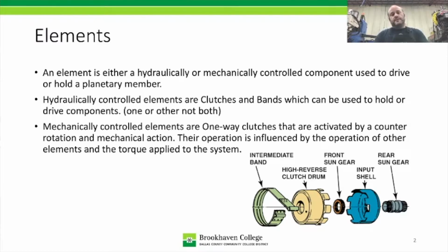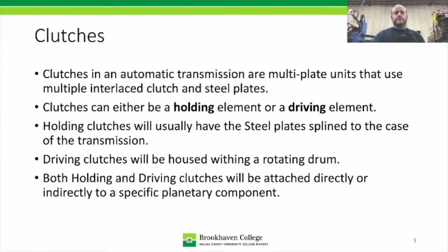And with the one-ways, their operation is really dependent on torque input to the system and whether or not the vehicle is accelerating or coasting too. So you have a one-way involved in, let's say, 4th gear. You can give it gas, the engine will rev, it'll catch that one-way, and you can accelerate. But when you let off the gas pedal, it's not like in a manual transmission. The engine will actually idle down, but you'll still be able to coast. It's just like riding a bicycle: while pedaling you can accelerate, but you can stop pedaling.